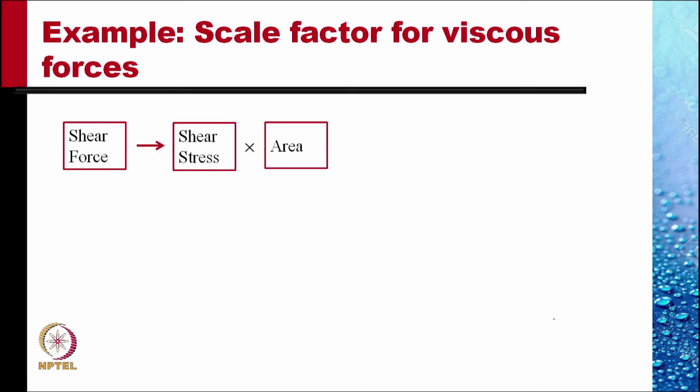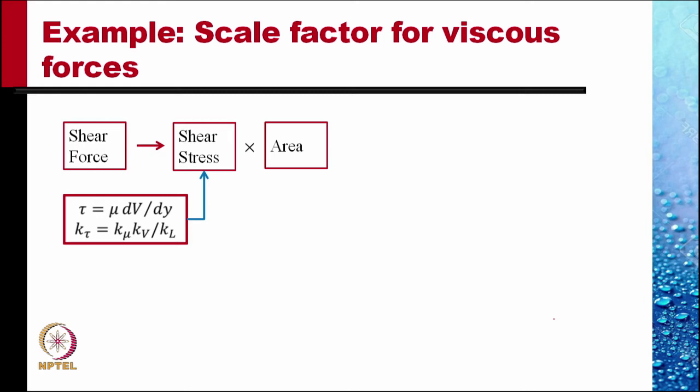Let's do an example. Let's find out the scale factor for viscous forces. Viscous forces are shear forces, which will be shear stresses times the area. The shear stress, tau, varies like mu dV by dy, the Newton's law of viscosity.